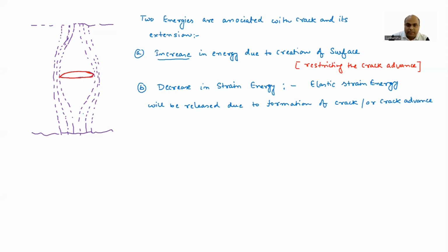So there is a decrease in strain energy because of the formation of the crack. Since the energy of the system is decreasing, this is going to be the driving force, isn't it? So this is the driving force for crack extension.